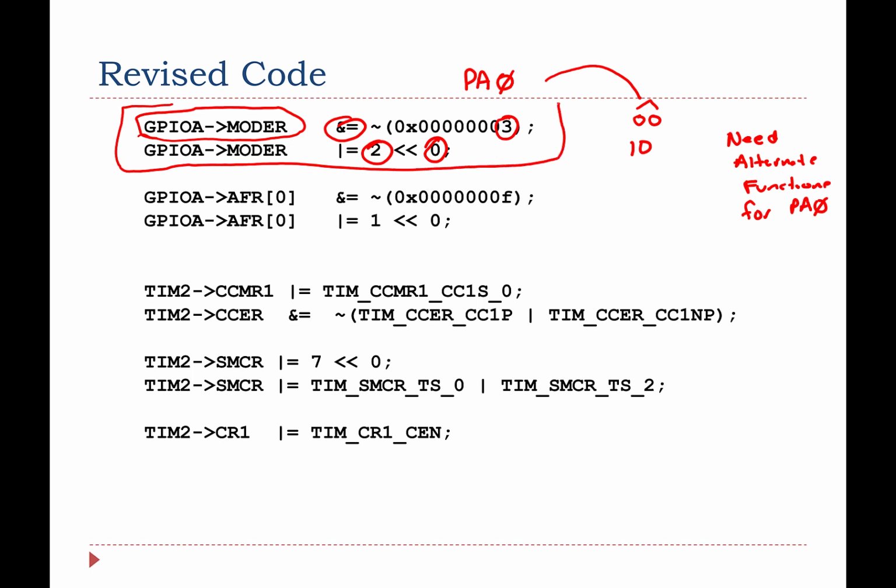So you're going to see this as a set of revised code for our templates for the timing parts. Now what's this? This is looking at the GPIO registers, and it's looking at the alternate function register. Within the GPIO registers, there's the alternate function register, and you can also see this sometimes written as AFRL for the lower bits of that.